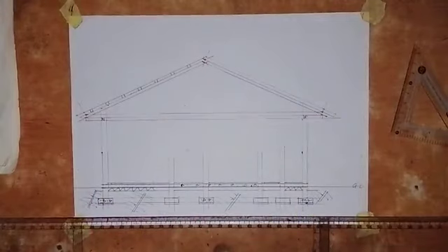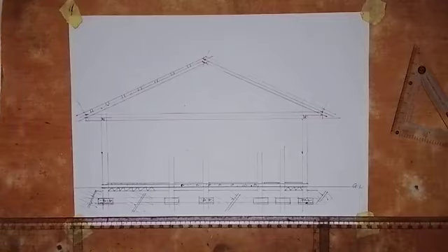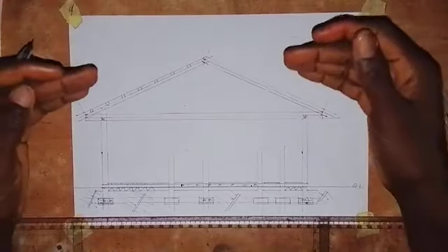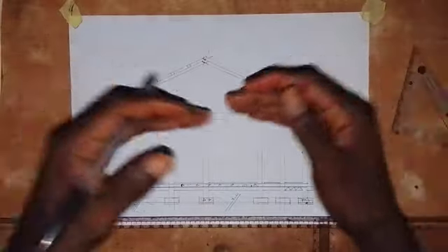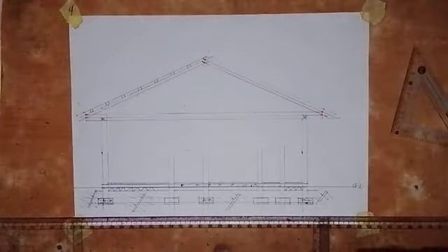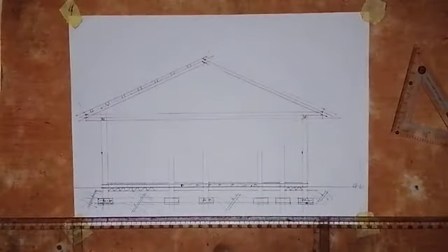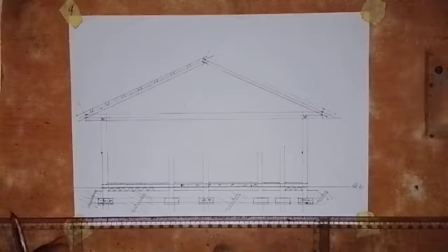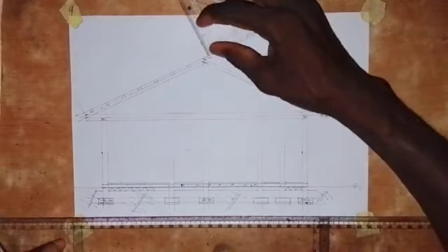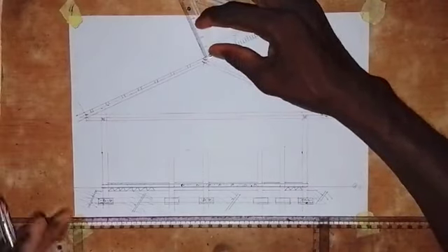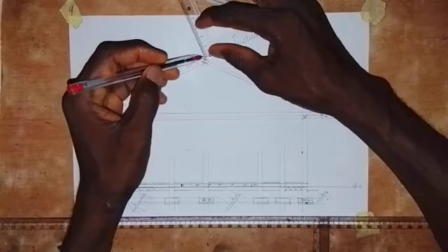So having done this, we have to place the roofing material. That's the next thing that we are going to place here. The roofing materials are laid on the purlins. So just repeat the same thing as I did here. That's very important. So now let's put the roofing material. For the roofing material, let's make it something like 1.5 so that we can see it.